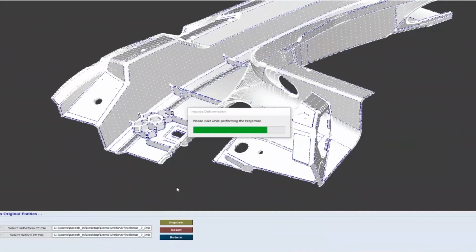So this is how quickly and efficiently we can get a new warpage compensated CAD in MeshWorks. Just give a minute or so. Let's assume you have a large component and then you follow this step, and that's how you can quickly go ahead and create a new CAD, and you can do the die phase study.